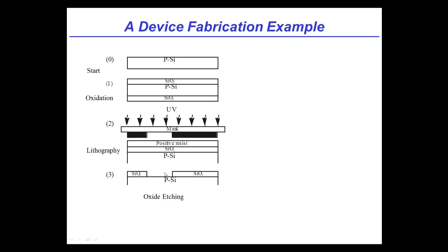So looking at this, it looks like you performed anisotropic etching here, and I'm saying that because these lines appear to be pretty straight. Yeah, that's okay to assume that for this example. Okay, all right, great. So now we've gone through a lithography and etch step. Let's go ahead and proceed to use this oxide window.